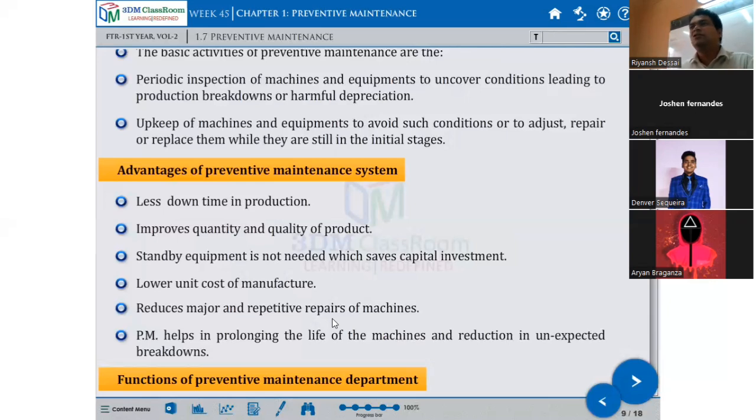The chiller chills the water and sends it to the plant. With the help of that chilled water, you can cool so many rooms. Every room has a cooling coil. The chilled water flows, and that chilled water cools the coil. There is an air blower with a filter, and that air blows over the chilled water coil, the air gets cooled and enters the room. Actually, it starts from the chiller. If you maintain one chiller well, you can save the cost of another. So, understood? That is what a standby pump or standby machine means.